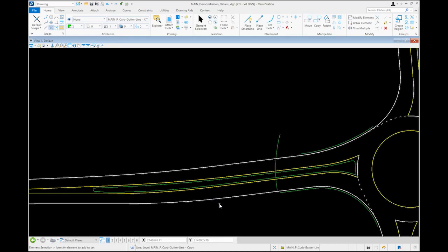The other thing to consider is what we're tying into in terms of our approach typical section. So commonly, you would have at least a 5-foot paved shoulder that would allow for use by cyclists along the outside. So for this east-west state route, we would assume that we have a 5-foot shoulder that we're tying into. Carry this up. Between these areas, we're going to have to transition from our 2-foot curb face offset back to our edge of our 5-foot shoulder. Same here, we'll need a transition zone.